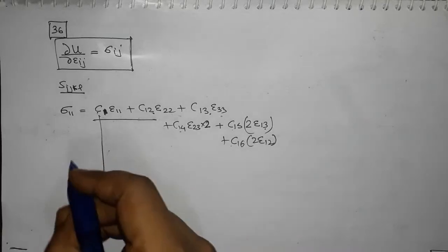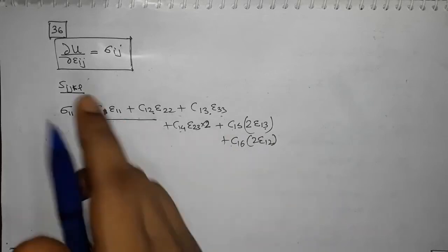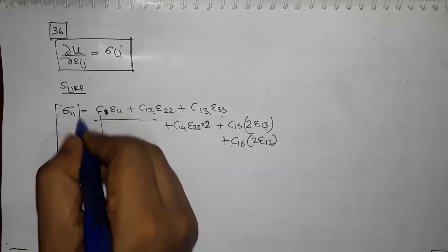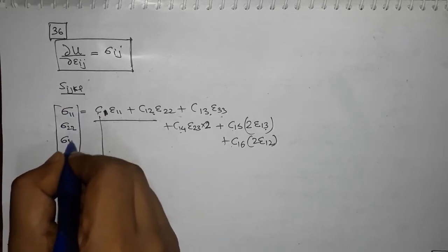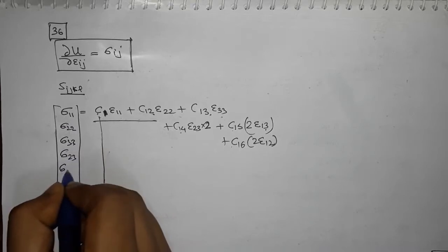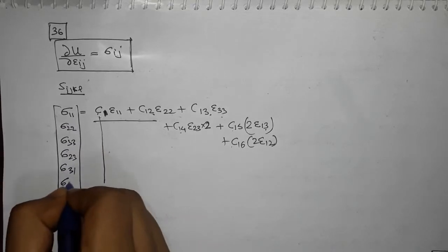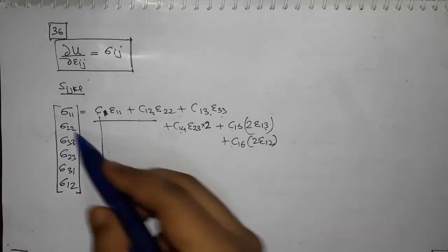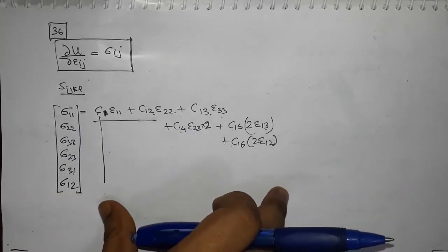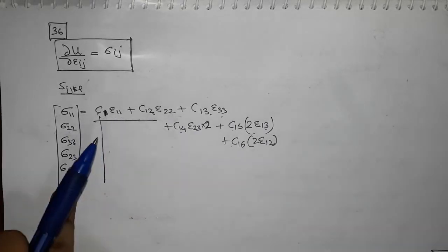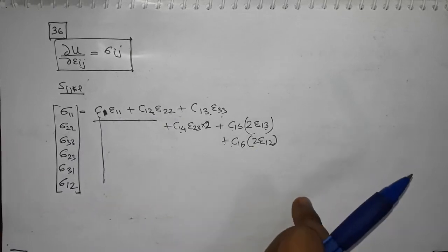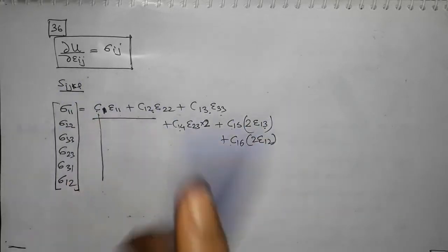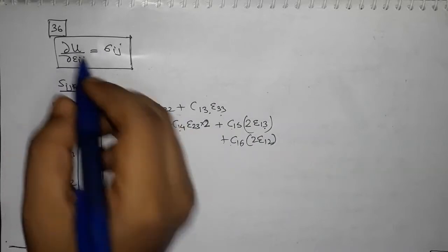and this is what I showed you at the start of the lecture, where we dealt with a 6 by 6 matrix and the stress vector, if you remember, for our plane strain condition. So sigma 22, sigma 33, sigma 23, sigma 31 or 13, and sigma 12. Okay, so now we are changing our dimensions from 3 cross 3 to 6 cross 1. This is 6 cross 6, and then strain of 6 cross 1 again. Okay, so now we write like this,